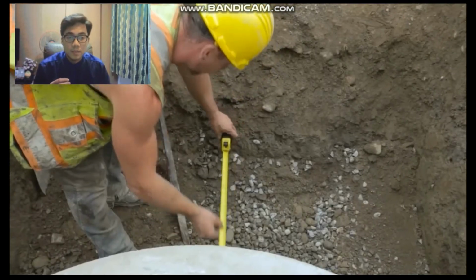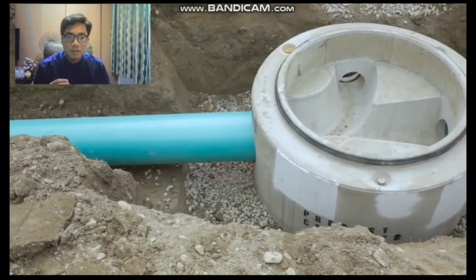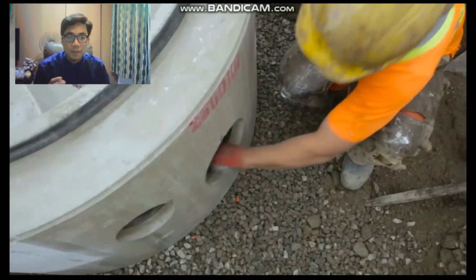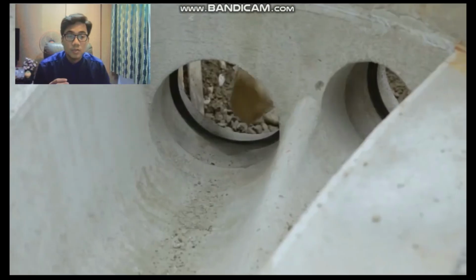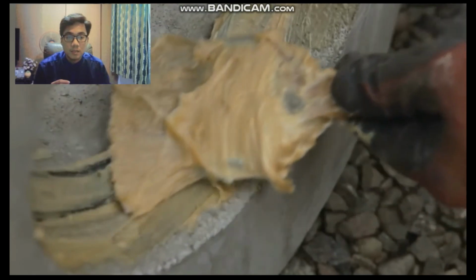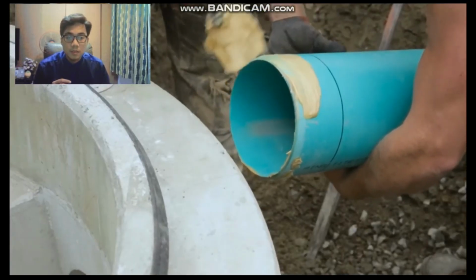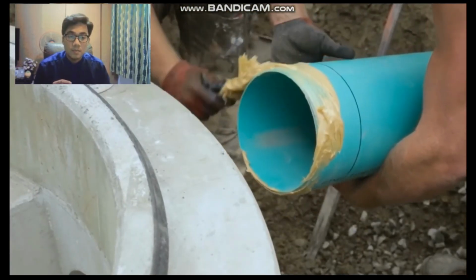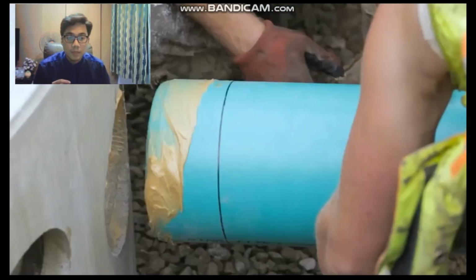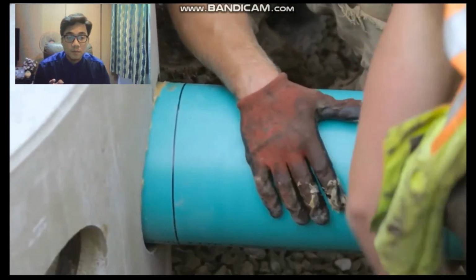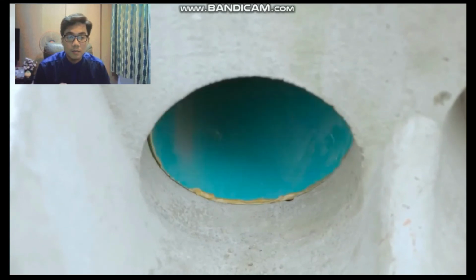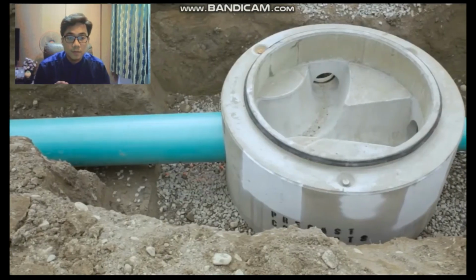Make adjustments as necessary. For placement of an upstream pipe, again measure, cut and chamfer the upstream pipe and place it in line in the trench. Clear the selected inflow opening of the manhole base of any debris and lubricate. Additionally, lubricate the upstream pipe, as with the placement of the downstream pipe. Align the pipe with the inflow opening of the base and push home until the pipe butts firmly up against the rear of the third step.